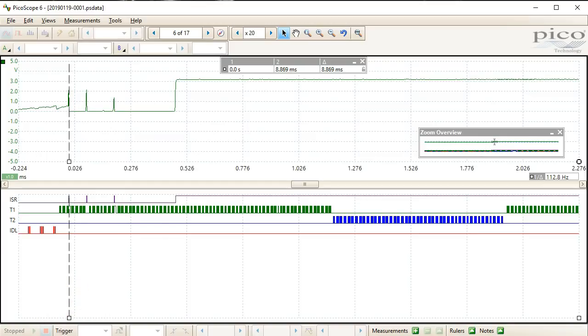But let's analyze this trace in detail. As in the previous case, initially the semaphore had no tokens, so the Blinky2 thread blocked on the semaphore wait operation. The first falling edge caused the GPIO F interrupt to signal the semaphore, which added 1 token. But this time the Blinky2 thread could not run immediately because it could not preempt the higher priority Blinky1, which happened to be running.